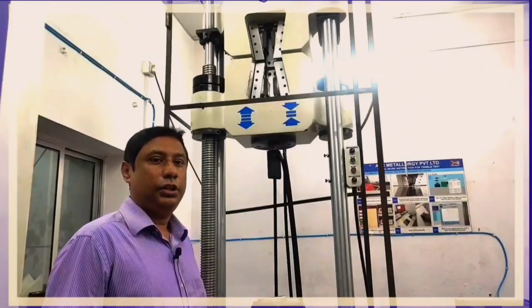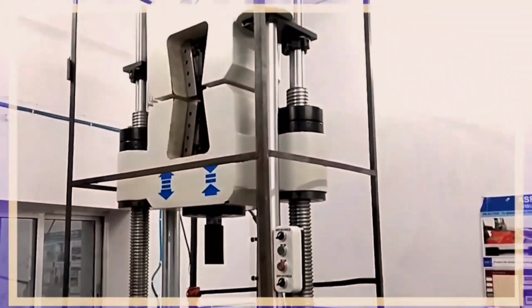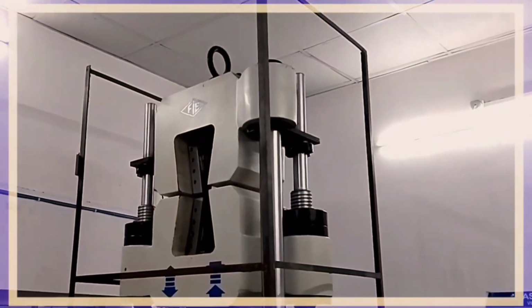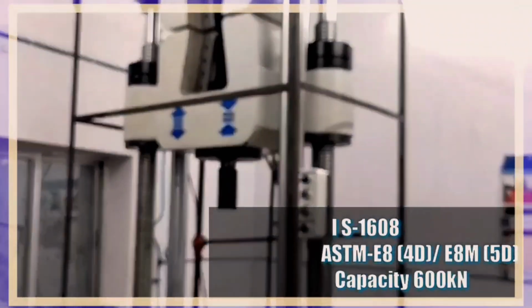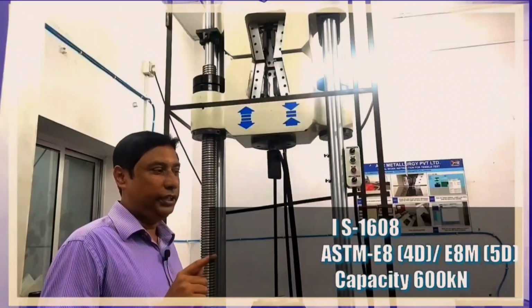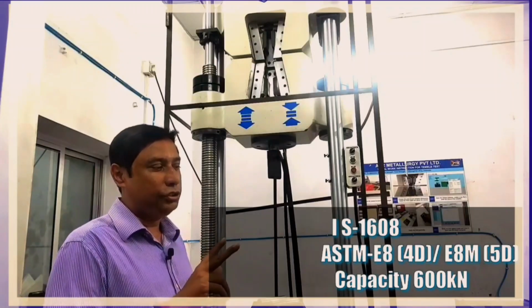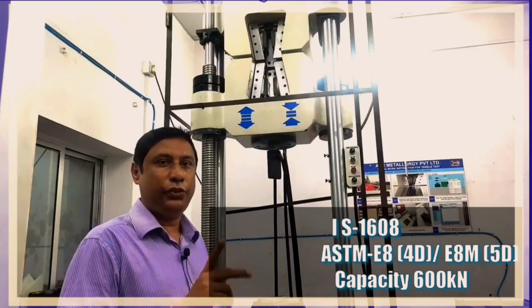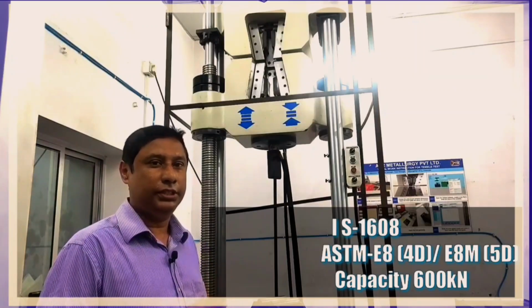Hello viewers, today we will talk about tensile testing. In tensile testing, IS standard IS 1608, ASTM E8 and E8M are used. What is the difference between E8 and E8M? The gauge length is of two types, 4D and 5D. E8 is for 4D and E8M is for 5D.